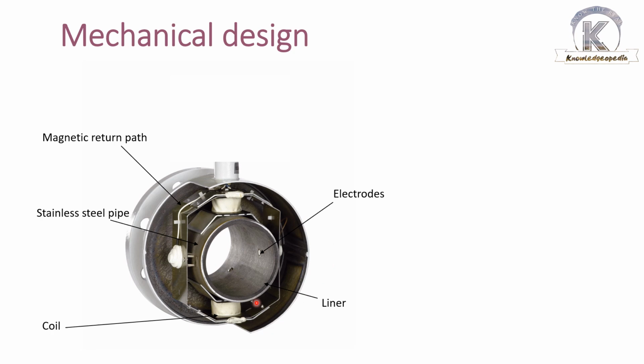It's a hollow body basically. Okay, so process connection, this is the process connection that provides connection to customer process piping. Choose from any option, that could be NC, that could be PN40, PN16, PN other, that screwed connection, that could be triclamp version for food and pharma. It's widely available, process connection depends upon the manufacturer one by one.